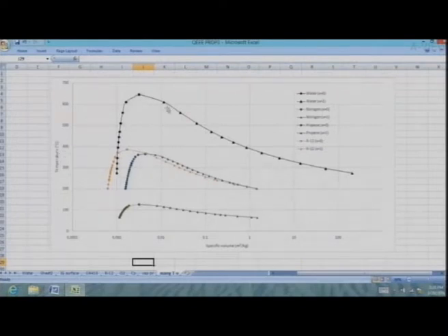This curve at the top is for water. The bottommost curve here is for nitrogen. So you can see that it is going to very, very low temperatures there. Something like 126 Kelvin is the critical temperature for nitrogen. And in between here, there are two things I have drawn. One is propane, which is this curve, and just next to that is this curve, which is for R12, CCl2F2, which is a refrigerant. And we can see the range over which these properties vary.